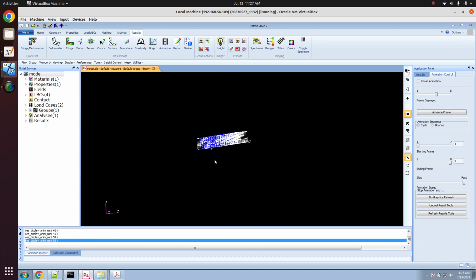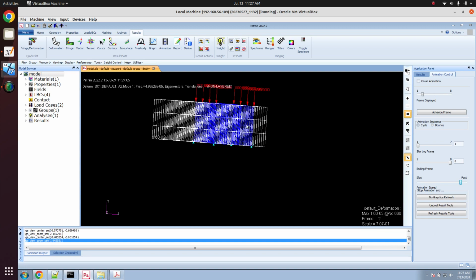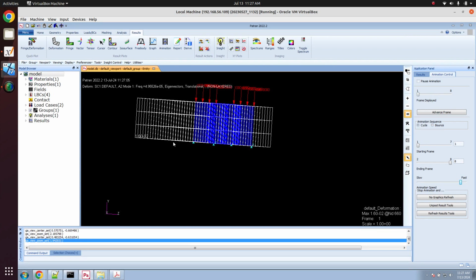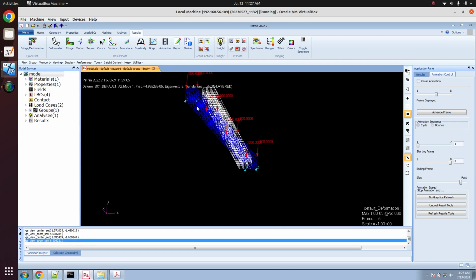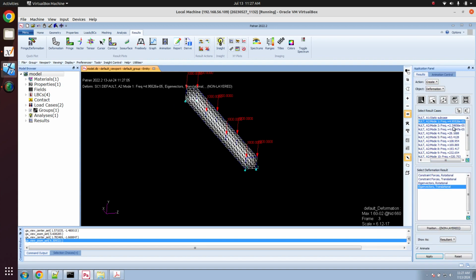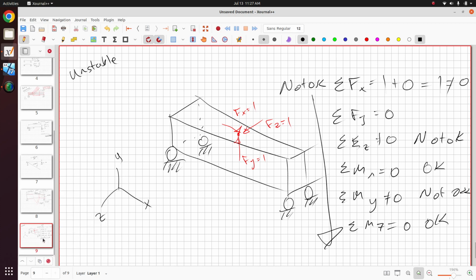The results, the mode shapes, can tell you which are the mechanisms, if you will, which are the rigid bodies. So here is one of the first mechanisms, or rigid bodies. Here, if we animate this a little. So remember, this is a structure supported on some rollers. So you could think that this structure is allowed to move left and right along the z-axis. So this is the first rigid body. So this can help you determine, okay, this structure is not supported in the z direction. So that's a problem. We have to fix that. Now, when you look at this, every rigid body is going to have a natural frequency close to 0. Here, you don't get exactly 0. Here on the right, you get 4.99e-5. So let me go ahead and pull this up real quick.